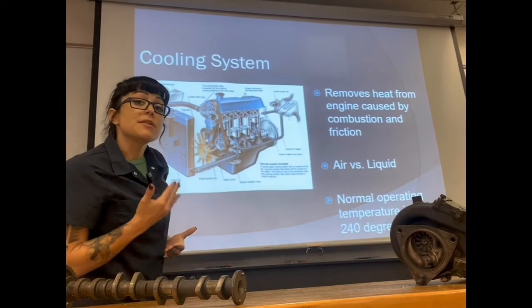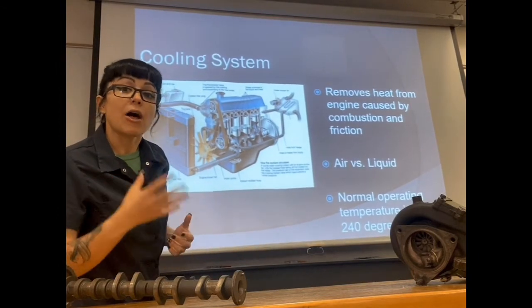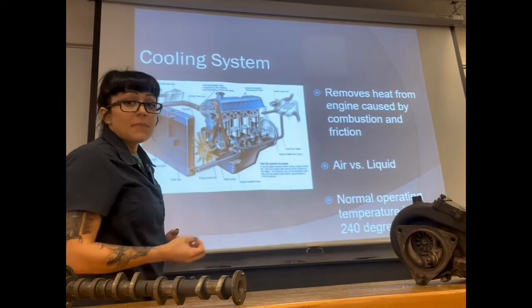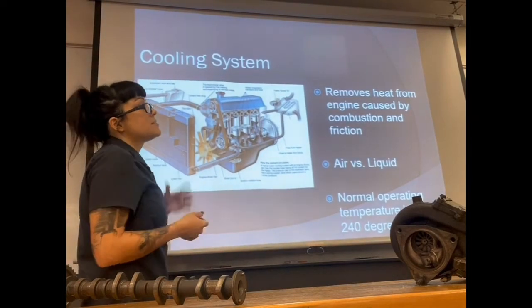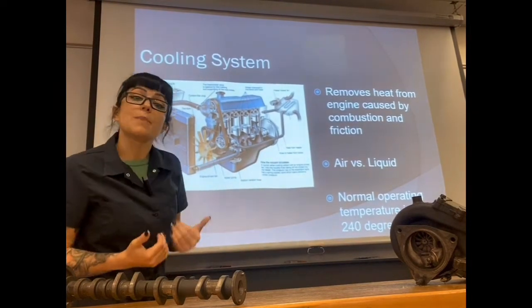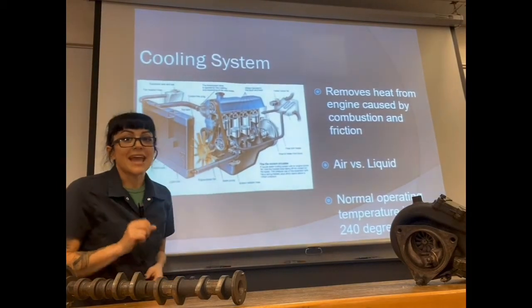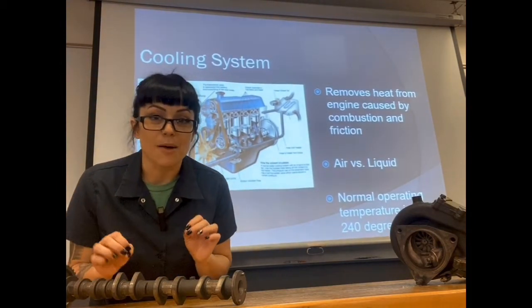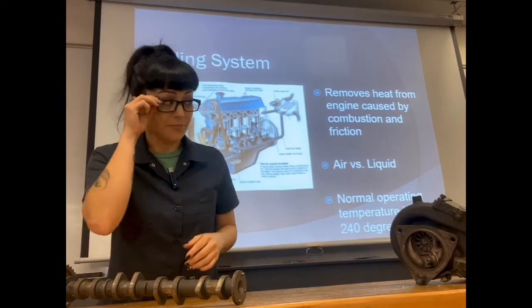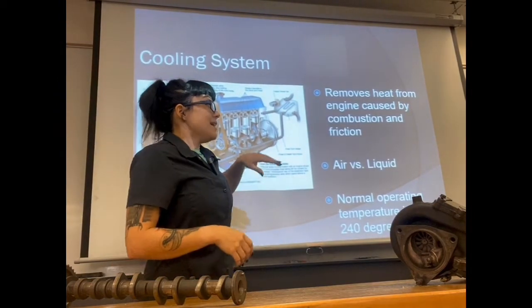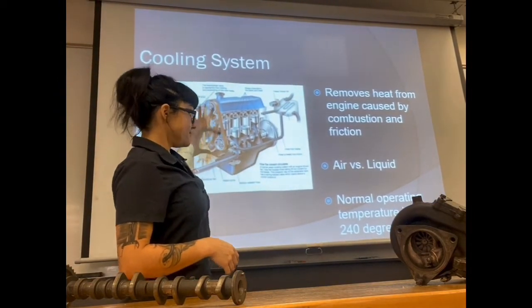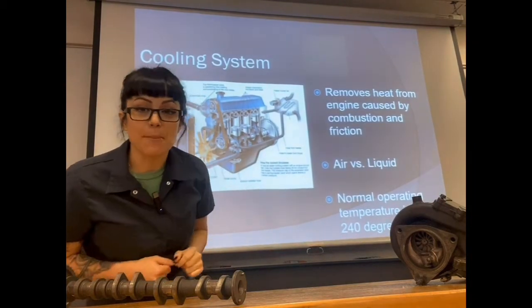So after lubrication system, we've got our cooling system. Now, I did mention that the lubrication system does help a little bit with cooling, but the main job for our cooling system is to remove heat caused by that combustion and the friction. But it also has a little hidden job that not a lot of people think about, and that is to actually keep our engine at a normal operating temperature.